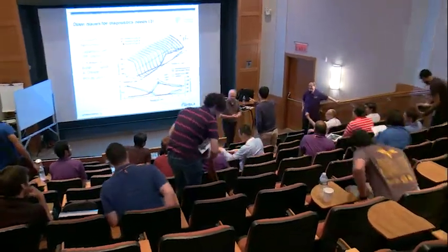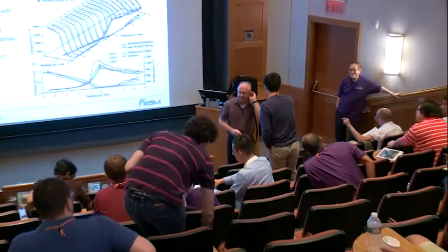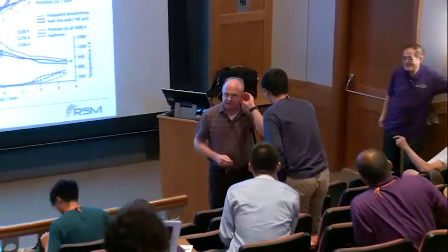So for the 40 micrometer, which layer of the boundary layer do you use? Is it the viscous, buffer, or inertial layer? The question was about what we can resolve within these boundary layers, whether the 40 microns is sufficient to look into the sublayers. And the viscous layer, I would say, for this case, would be resolved. With the 40 microns, I would expect, yes. I think it's sufficient for that.